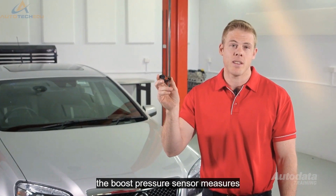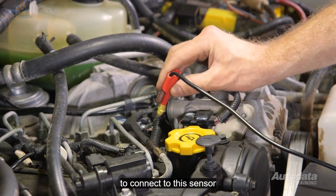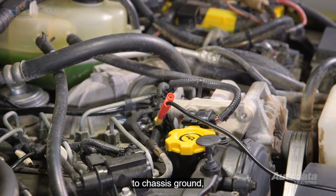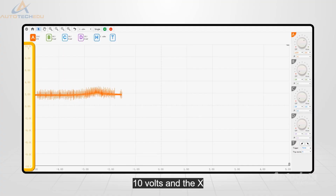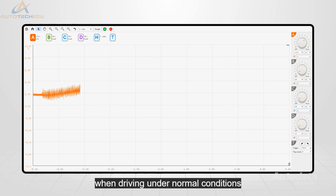The boost pressure sensor measures the turbocharger's boost pressure. To connect to this sensor, backprobe the sample lead to the signal circuit and the black to chassis ground. Adjust the Y-axis to 10 volts and the X to 1 second for the best trace display. This is what a correctly working sensor looks like. At idle, the trace sits at a constant 2 volts. When driving under normal conditions, the higher charge air pressure causes the trace to rise.